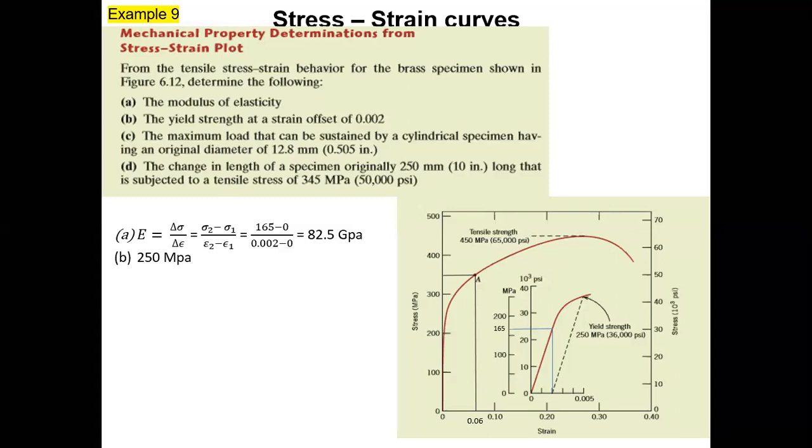There is a maximum stress that a material can bear. After that maximum stress level, it starts necking and subsequently it will break. So the maximum stress means the maximum stress that the specimen can take. That strength is what we call the tensile strength of the material. Tensile strength is the highest point of the curve and it is already given. It is 450 megapascal. This is the maximum stress level. So if the specimen diameter is this amount, how do you find the maximum load?